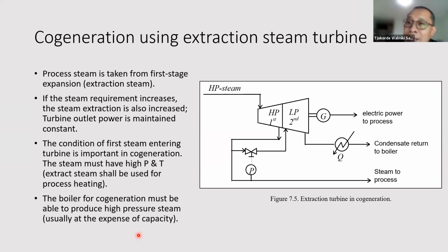Okay, so again, this is a very simple question, right? Let's say that you have a process stream that needs to be heated up to 100 degrees Celsius. So that's your heating target, right? So obviously you need a heating media with a saturation temperature, meaning the condensation temperature, of the steam higher than 100, so you can obtain an effective heat transfer rate.